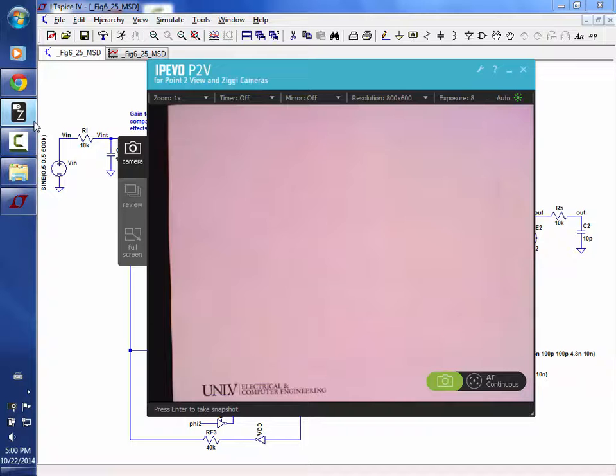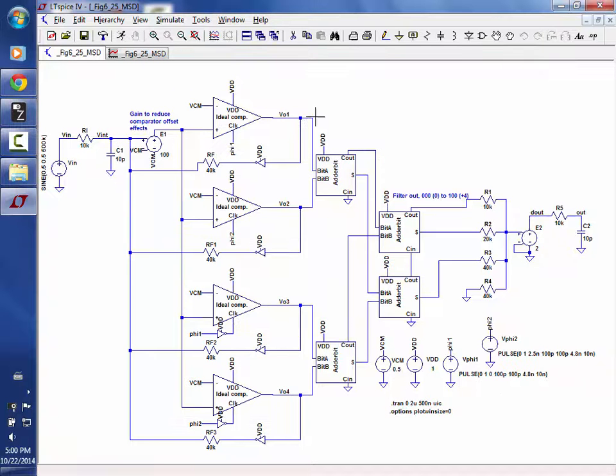But let me prove it to you. Does everybody see I'm adding all 4 bits together at any given time? Does everybody see these bits, because the clock phases are staggered by 4, are going to change every 2.5 nanoseconds? So the rate at which the sum changes, this is just a cheap D to A converter, the rate at which the voltage out changes is going to be 400 megahertz, every 2.5 nanoseconds, if there's a change on the input.